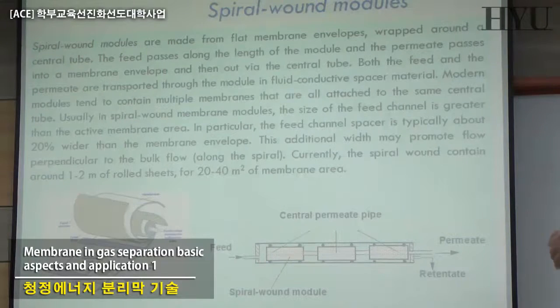Normally you have a nice long vessel, a long tube, in which you just include your modules. Normally there are 3, 5, 7, depending on the progress made. Today, easily 5 of these modules are present. With an 8-inch module multiplied by 3, that means 100 square meters of membrane, a few hundred square meters, also in flat sheet, can be present in a single module.